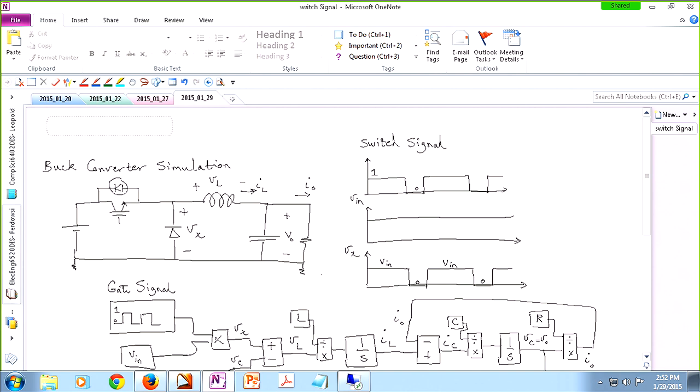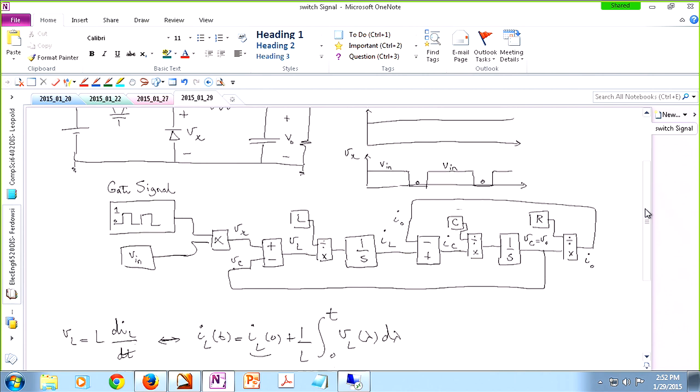You need some sort of a galvanic isolation from the input side to the output side. So if you have a fault current circulating in the system, the output side and the input side are kind of decoupled from each other. Or sometimes, actually, your input and output do not have the same ground. For instance, let me give you an example.